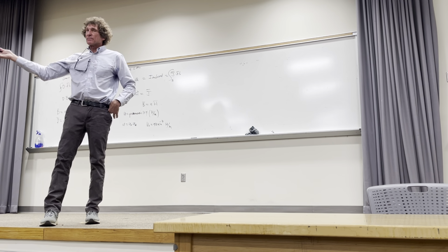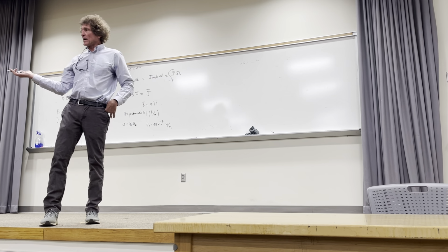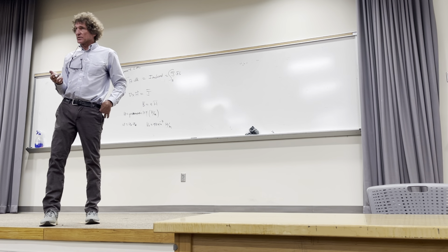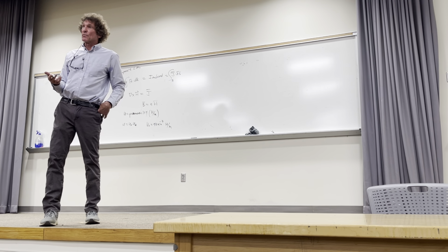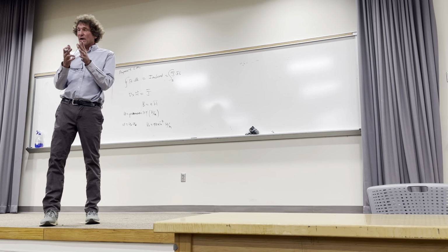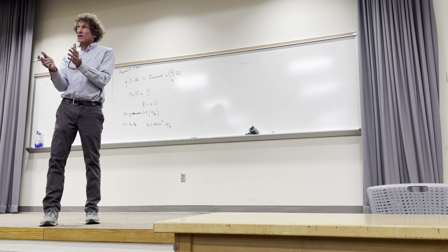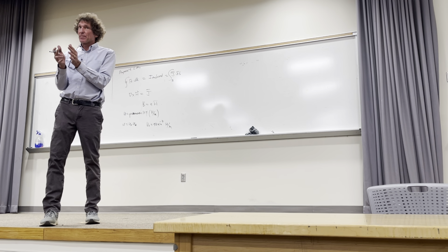Now, what's the frequency of the wall outlets here? 60 hertz. What is it in Europe? Anybody know? 50. This is much better than my normal class. All right. What is it for space-based transformers on satellites? Anybody? Low frequency. 400 hertz. At least it was, unless they've changed it. All right. There's all these standards. All those low frequency things are great to work around iron core transformers that have high values of mu.